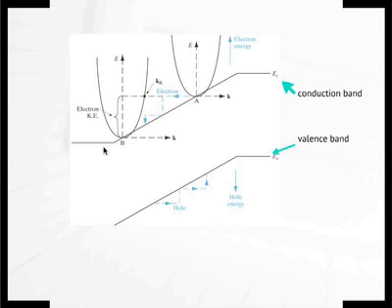Okay? And the electric field is applied in this direction. Sorry, in this direction. Okay? Now, we can also correlate this with the E-k band diagrams, which is the more complicated structure. And essentially all that means is that the band diagram is shifted up in energy relative to each other. Okay, so you can see this band now moves up when electric field is applied.